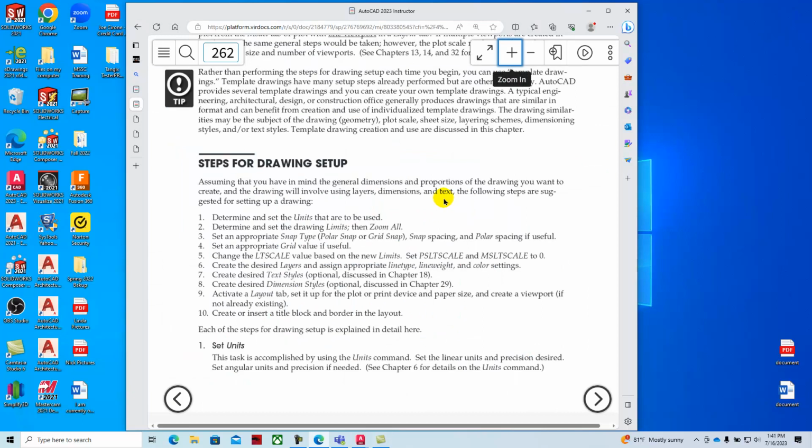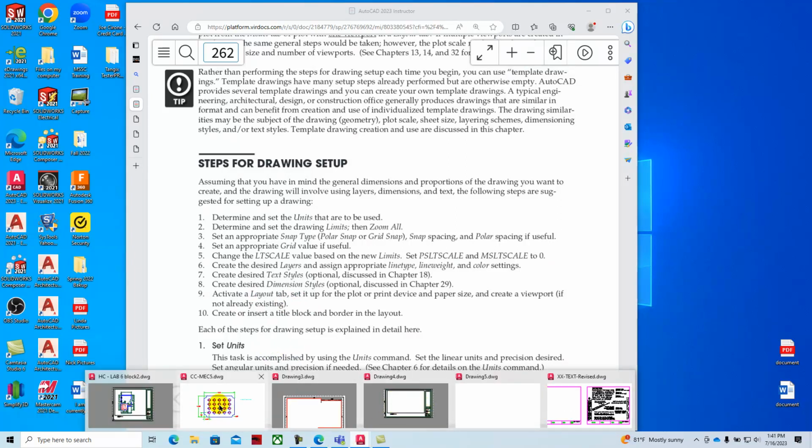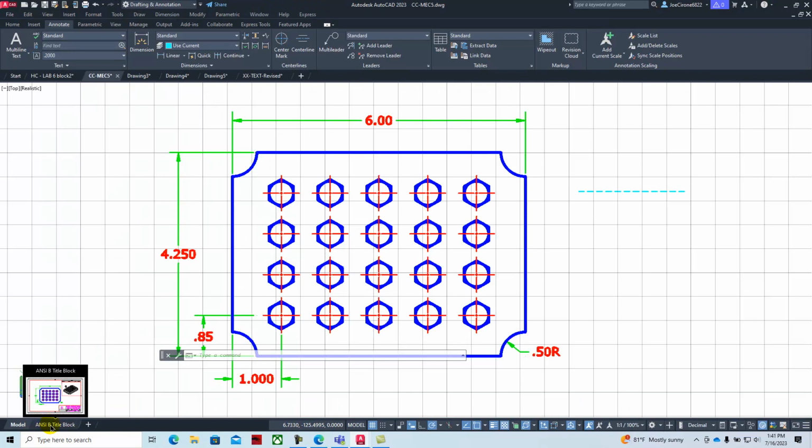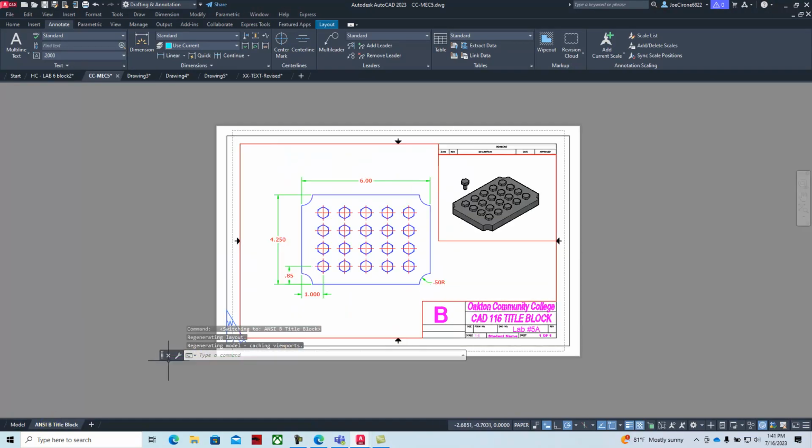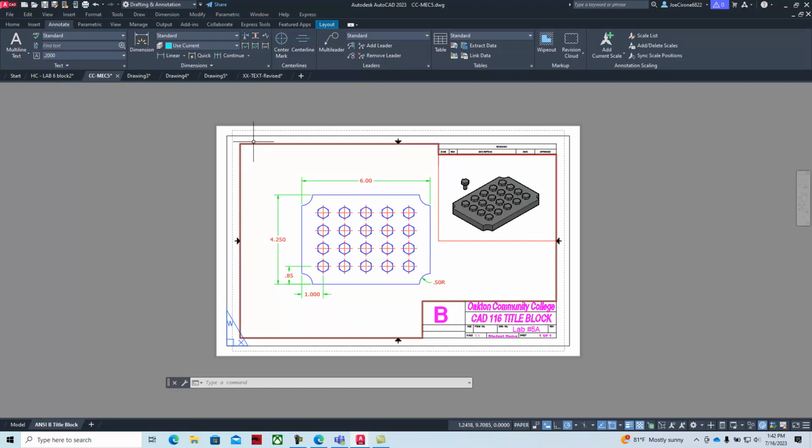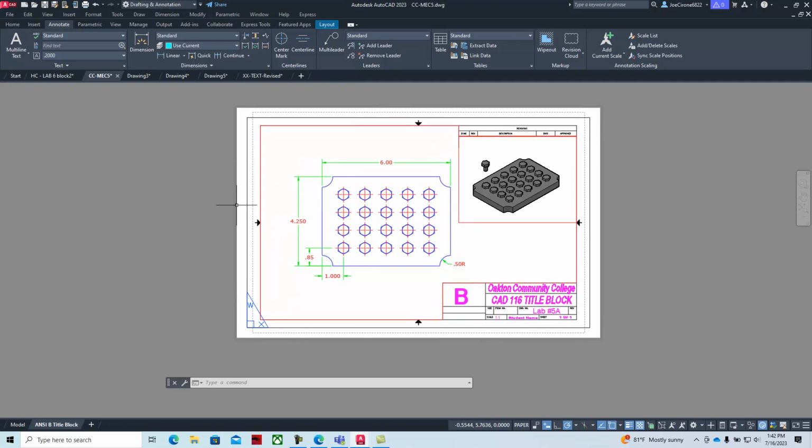And so as we look at our textbook readings, these are basic settings that we use within a drawing. And then lastly, they talk about the Layout tab. And so the way the Layout tab works here is that we have these mechanical drawings, and then here's our tab for paper space. And in paper space, or layout mode, what it does is it puts the paper on for us. So this is like a preview of what the plotted sheet would look like on paper. And then there's what's called a viewport, and then the viewport is scaled for the object to fit within that.